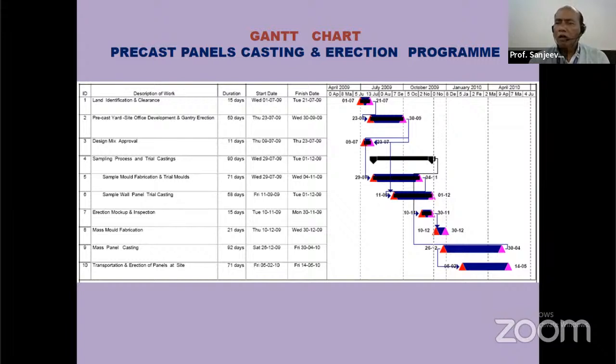Based on this program, the start date, completion date and number of days are given for the activities: land identification and clearance, precast yard site office development and gantry erection, design mix approval for the concrete to be used, sampling process and trial casting, sample mold fabrication and trial molds, sample wall panel trial casting, erection, mock-up and inspection, mass mold fabrication, mass panel casting, transportation and erection of panels at site.